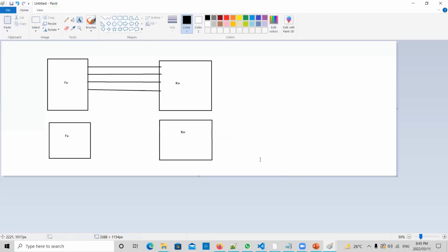In the case of serial, they transmit bit by bit. They have a TX line, and the 8 bits go serially to the receiver. When you do it like that, you have a problem. When you send a series of bits one after another, what is the division? Like, what is called one bit?